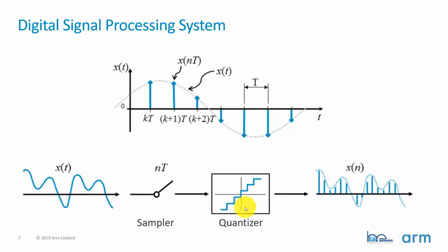So, for example, a lot of times you might have an analog digital converter that gives you 0 to 1023 for values. Maybe you'll have 0 to 4094 or 4095. So you can imagine here that we have something that's going to quantize whatever the value is that's coming in, that's sampling, and give us a representation of what that actually is inside the real world representation of the signal. And the hope here is that, here's a signal that we're trying to sample, and digitally we have just set values spaced over a period of time that represents what that signal is doing.